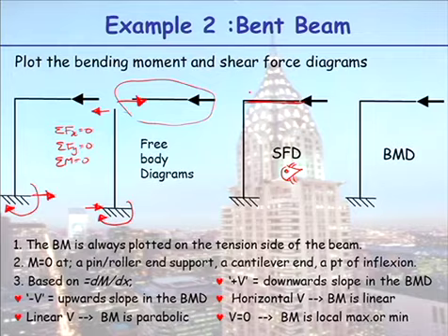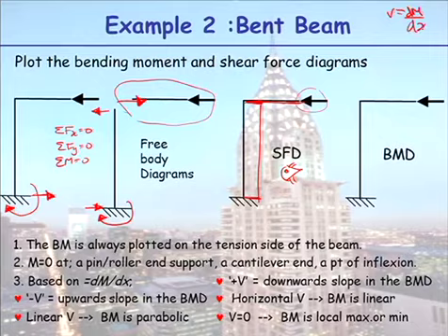So with respect to the vertical leg, you start at the left-hand end. Based on my eye, the left-hand side would be the bottom bit, and I step down, and then I move across, and there is a force to the left because that's my load. So I have equilibrium. So I have a zero shear here. V is equal to dM/dx. So that's not necessarily, as I said, telling me my moment is zero. It's just telling me the slope of my bending moment is zero.